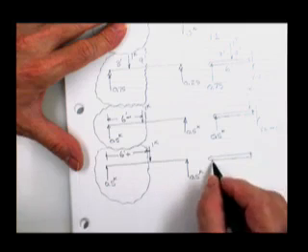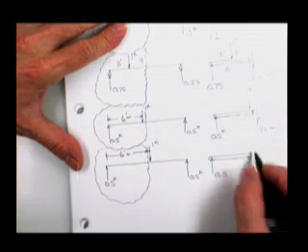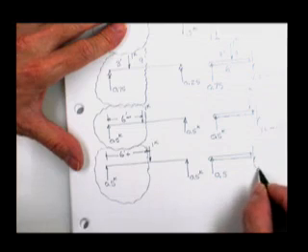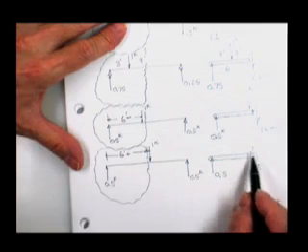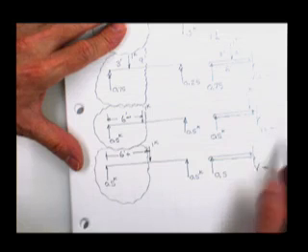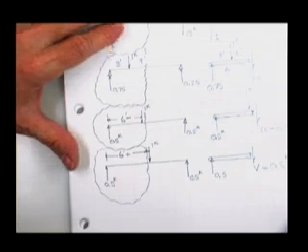This is still 0.5. Here's the shear. They're always going to be shown down on the right. That's what a positive shear is. Look at what happened. All of a sudden, the 1 kip load moved to the right of the cut face, and the shear changed from a minus 0.5 to a plus 0.5. Question?